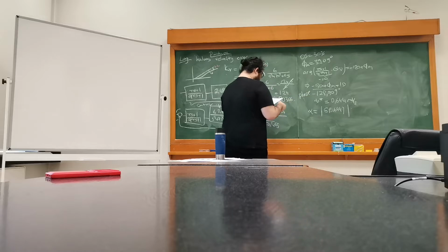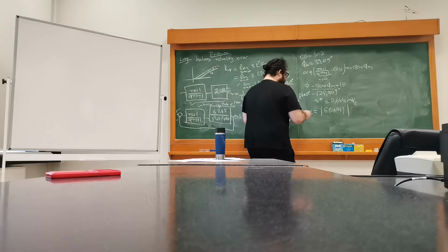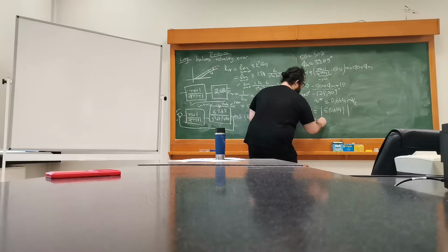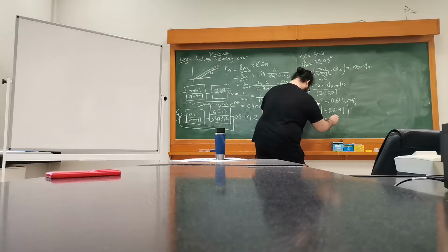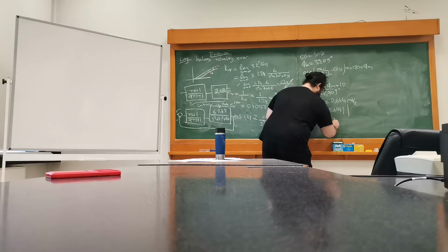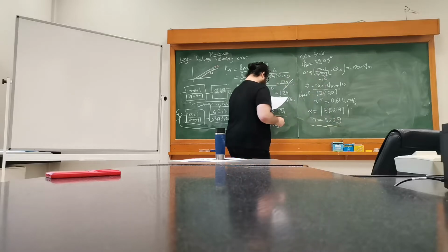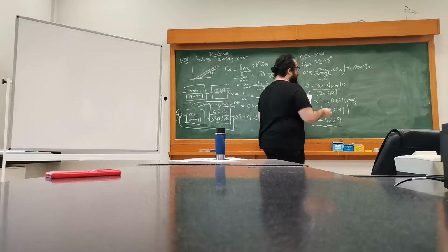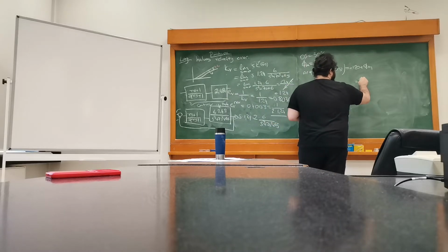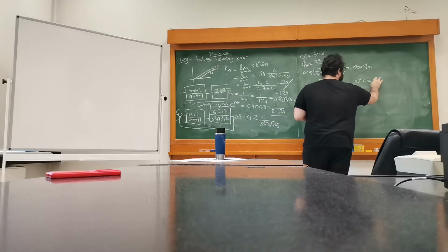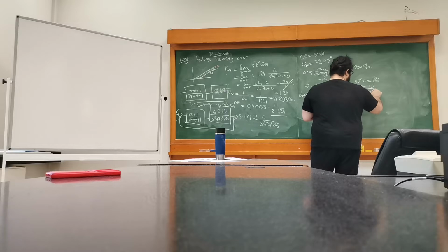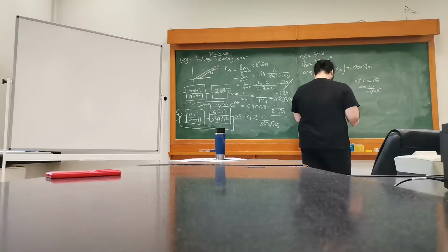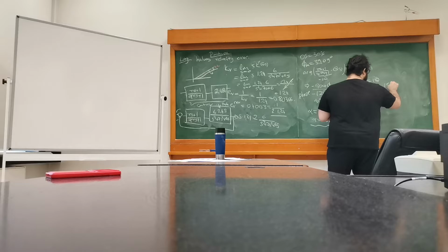So let's assume that we are using the updated Bode plot. You plug in this and find out that the alpha value for your lag controller should be 3.229. That's one part. And for roughly omega star tau equals 10, we have tau equals 10 divided by 0.644, which is basically 15.5.